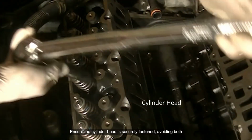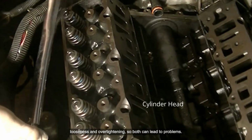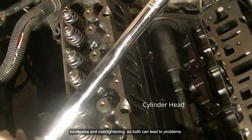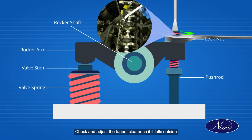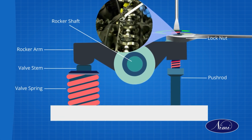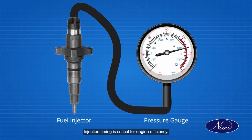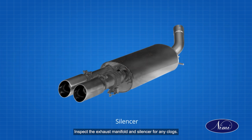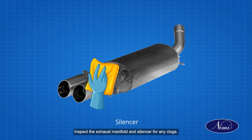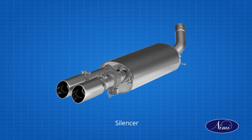Ensure the cylinder head is securely fastened, avoiding both looseness and over tightening, so both can lead to problems. Check and adjust the tappet clearance if it falls outside the recommended specifications. Injection timing is critical for engine efficiency. Reset it if necessary. Inspect the exhaust manifold and silencer for any clogs, cleaning them to maintain proper exhaust flow.